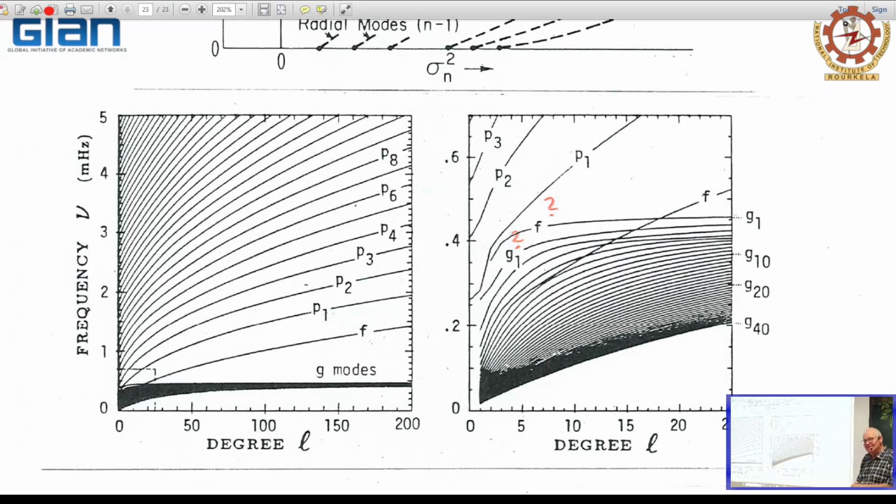I would not agree with this classification, and you will see later on why I would not agree with it, and why this mode is still the F mode at this position, and down there. And the G1 mode is still the mode on the right-hand side of the crossing and on the left-hand side. And this one remains the G2 mode from here to here, even if it is crossed by the F mode.